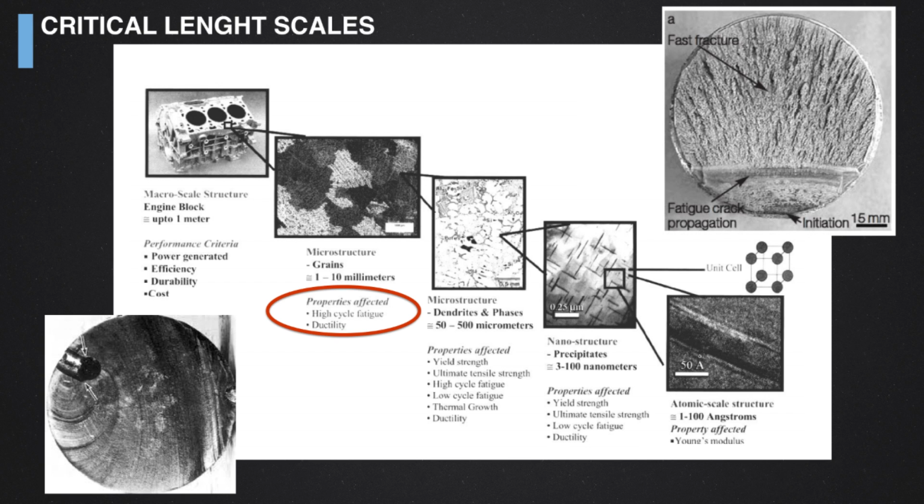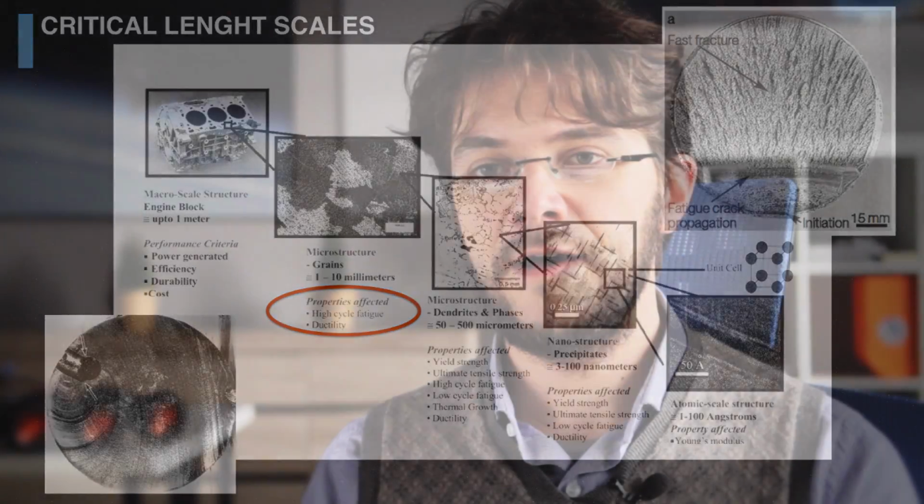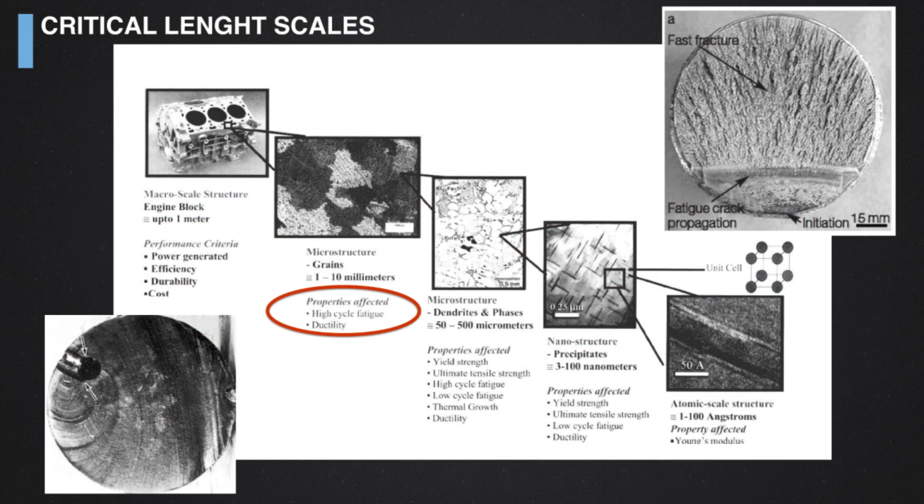What happens normally is that if you have a failure and you watch under the electron microscope at the fracture surface, you are able to understand what happened and why the structure failed, and how it is possible to reduce the probability of going through such a failure. You see that the fracture is divided into two different surfaces. One which is a little bit even, and another one which is very opaque and has clear directions.